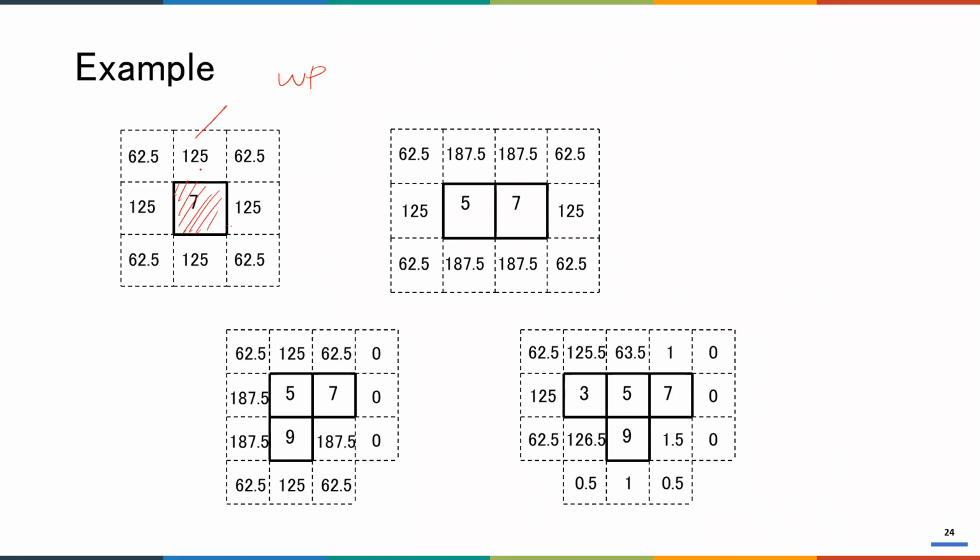Because this location will be adjacent, it means 100 multiplied by 1, because the adjacency status is equal to 1. And this location is 125 multiplied by alpha, which is half, so this is equal to 62.5. We calculate for all possible locations, and then we place it in the location that is appropriate. So in this case, we choose this location to place department number 5.